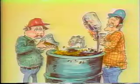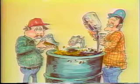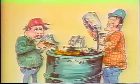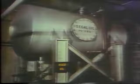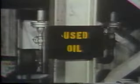After oil has been drawn into the container that you're going to use, be sure to replace the vent cap. Otherwise, dirt could get into the barrel. Now, once you've removed oil from a barrel, never return it to its original container. If you do, you greatly increase the possibilities of contamination. Contaminated oil can cause serious problems because dirt and other particles could get into a bearing and scratch or otherwise damage its components. All contaminated lubricants should be clearly labeled and properly discarded or recycled.